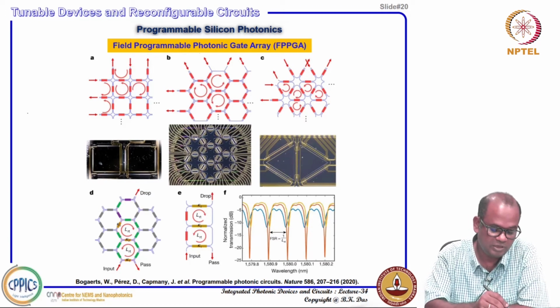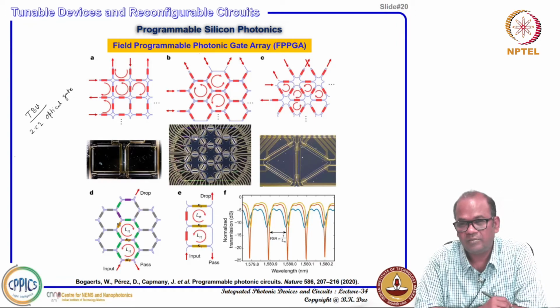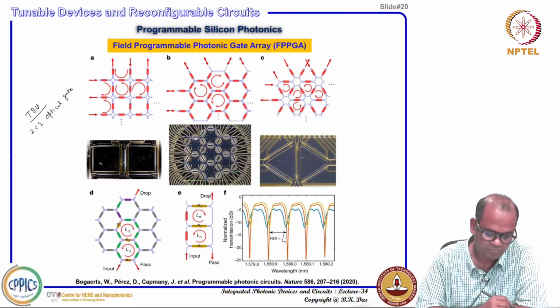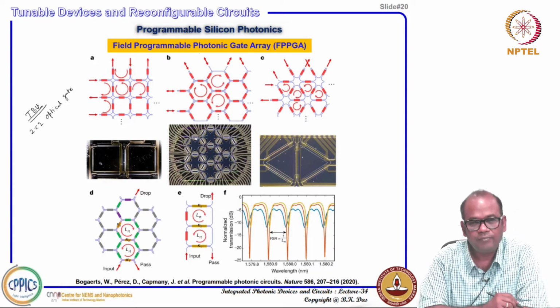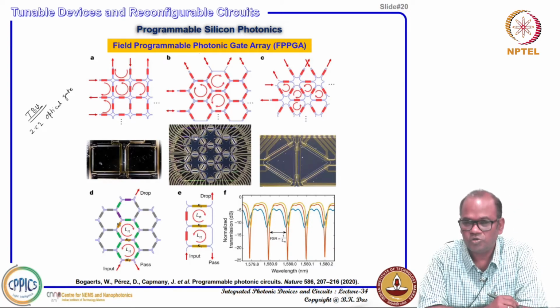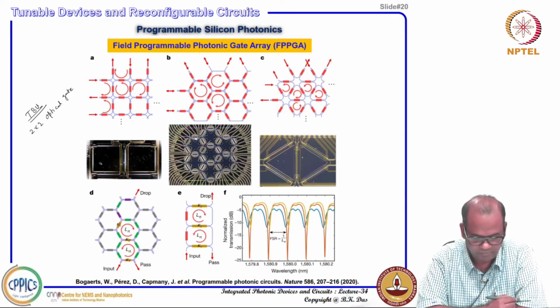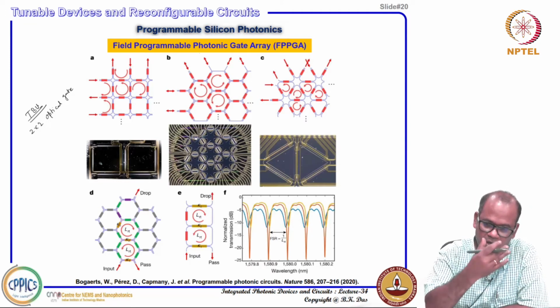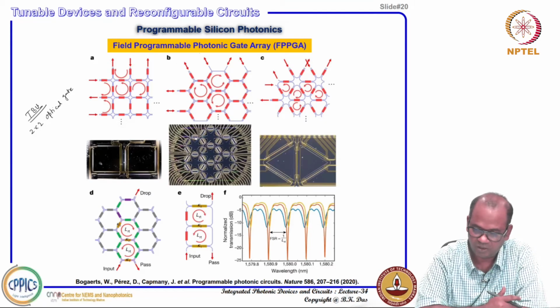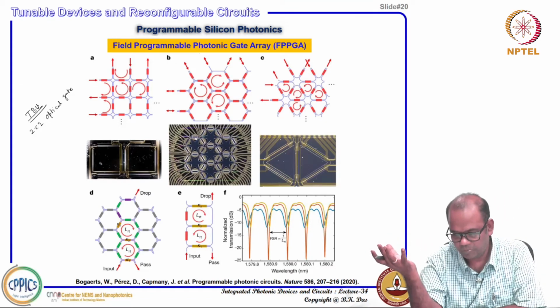So, you have the TBU, tunable basic unit, for 2 by 2 optical gate operation as a MZI, and it can be a ring resonator, optical gate, 2 by 2 optical gate. Okay. That is basically MZI or micro ring resonator as discussed. And these TBUs, we have shown how that can be used for a switch fabric, people demonstrated already, and you can program individual TBUs to get a certain type of output.